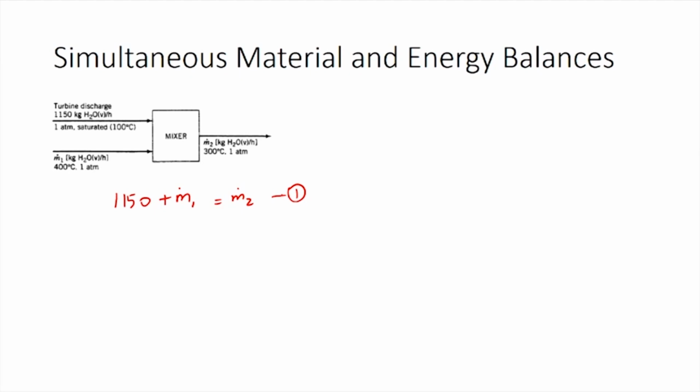So, here we would use the energy balance to the rescue. The energy balance equation for this open system would be delta H dot plus delta Ek dot plus delta Ep dot equals Q dot minus Ws dot. Considering that this system does not have any acceleration or change in position, we can ignore the kinetic and potential energy changes, so these two terms go to 0.